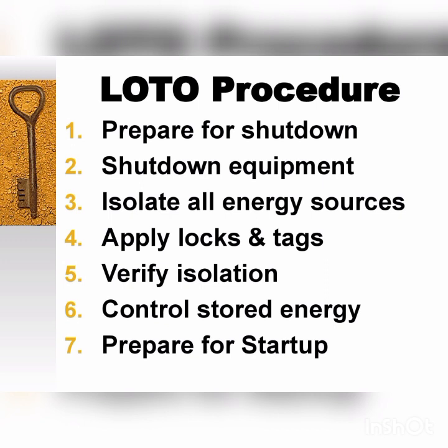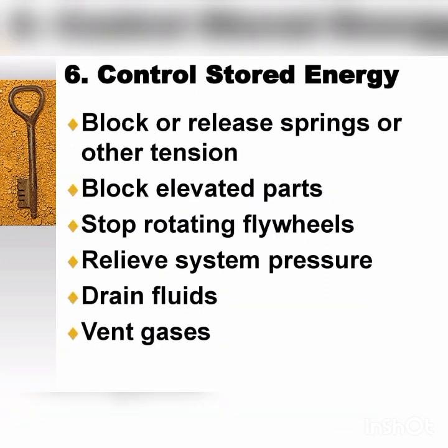Once the isolation is done, you need to make sure that the equipment is perfectly isolated and that the persons who are working are safe to work on it. Controlled stored energy: sometimes some equipment, even though switched off, has some energy retained in it. You have to make sure that all the energy retained in that equipment is completely released.